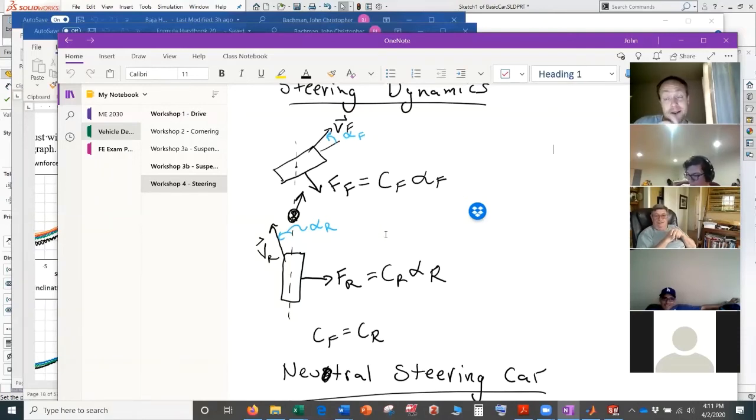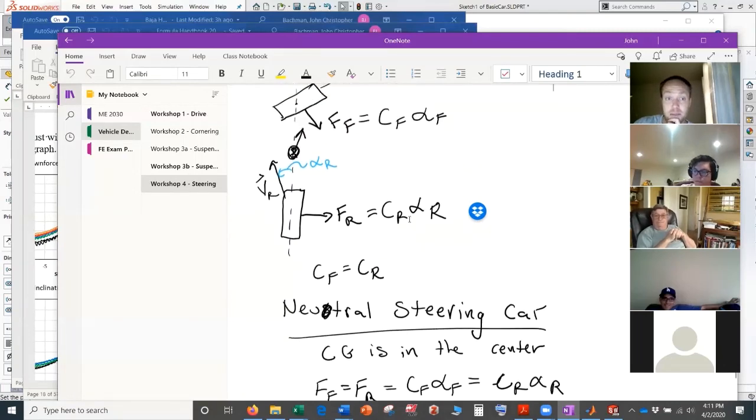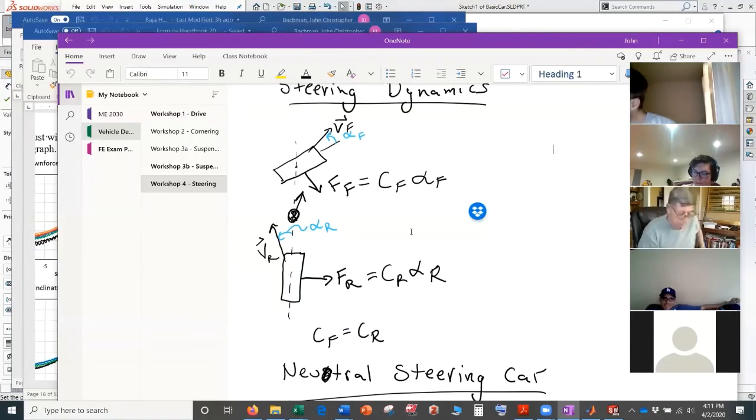So what does that basically mean as a result? Since both of these angles are the same, and this angle, when we go up, we'll call this delta Acker. This is your Ackerman angle, right here. It's basically the tire from going straight. So if we rotate this back tire so that its velocity is going straight, you'll notice that the velocity of the front will go exactly in line with the Ackerman angle.